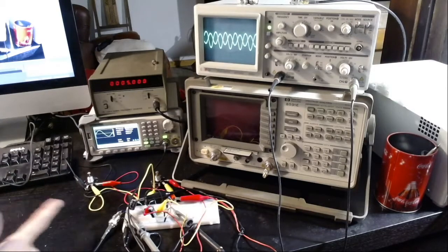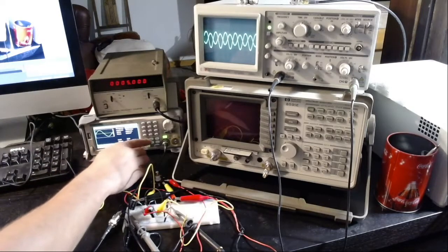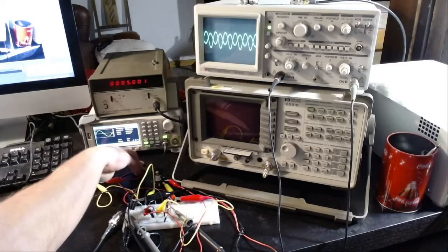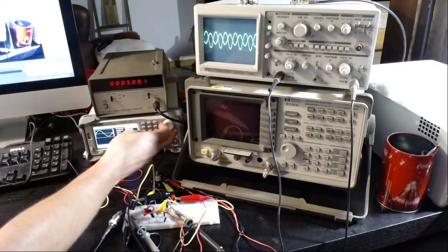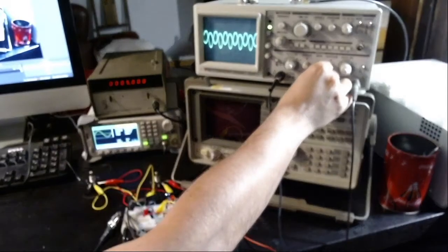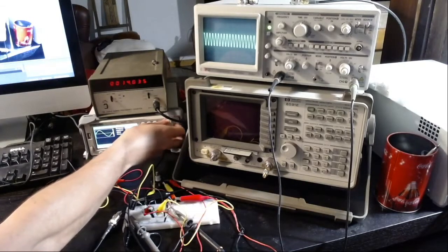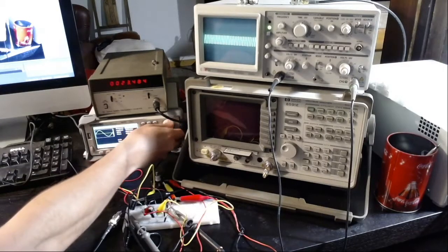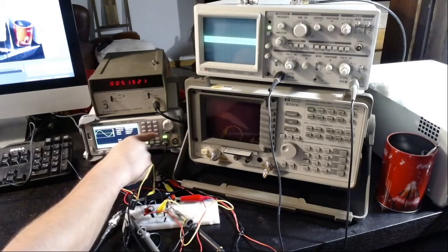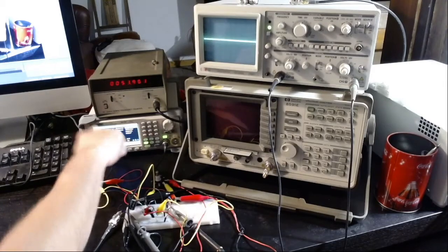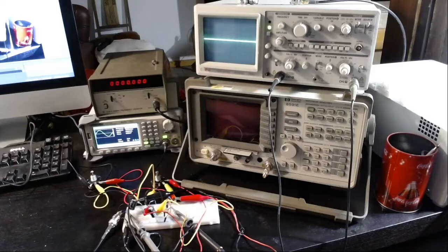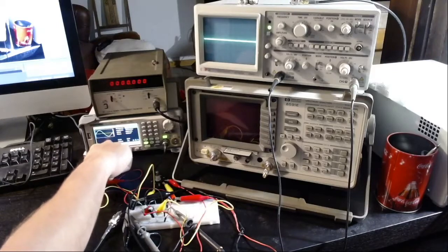The second specification was to amplify only the low frequencies and not the high frequencies. So let me show you that this is indeed the case. At the moment I have the frequency at 5 kilohertz. So let me just show you the amplified signal, so channel 1. And if I increase the frequency, you can see that the amplification is going down. I hope this is visible. We are at 30 kilohertz now, and it's clearly going down. If I set it to 1 megahertz, for example, it almost completely disappears. So the second specification is met. Let me go back to 5 kilohertz.